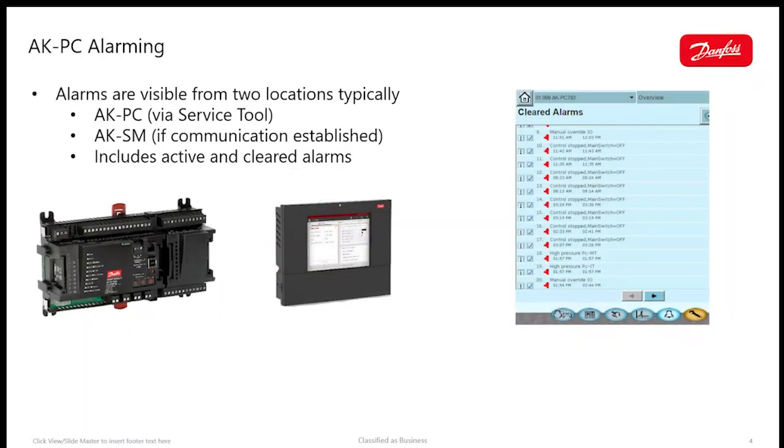Today's lesson, we'll be covering alarming configuration and also some of the standard alarms in our Danfoss pack controller as part of our AK PC training here. So for alarming of our pack controllers, there are two areas where the alarms will typically appear that a technician may be looking at to troubleshoot, investigate, and also for the notification itself.